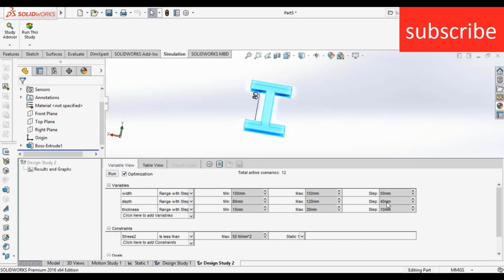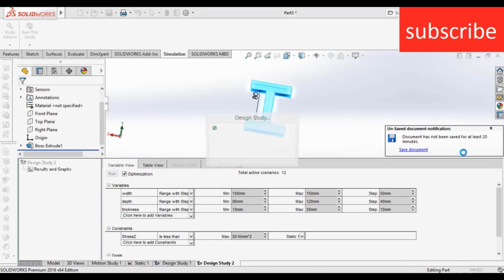But I am not doing it because when I do that, it is going to take a very long time and it is just a waste for me, because my main aim here is to tell you how to do a simulation. Okay, it is up to you how much quality you want. If you want much better quality, just decrease the step size to 1 mm or 0.5 mm as per your requirement. Okay, now click on run.